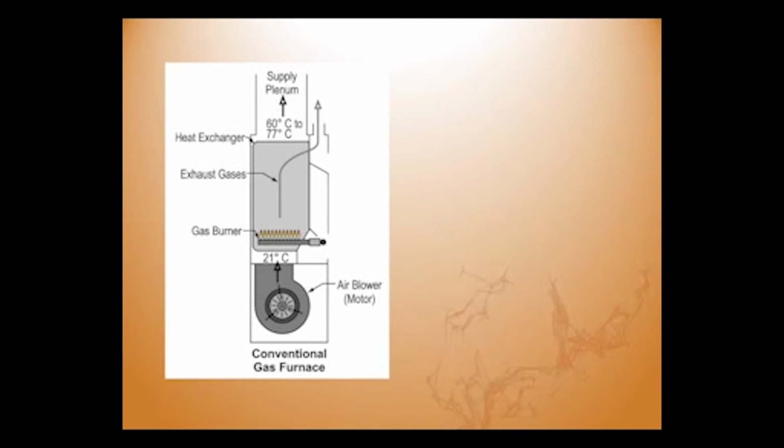Furnace designs have changed dramatically over the years, and it's all about utilizing as much of that heat as possible that we get from burning our fuel. Standard and mid-efficiency units tend to lose a lot of heat up the exhaust flue, which will exhaust hot combustion gases that condense outside. And this is when we see that white plume of smoke over top of a building. With this type of design, the combustion gases will exit naturally due to convection.